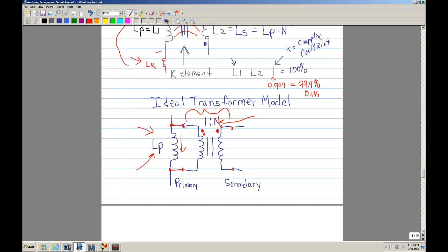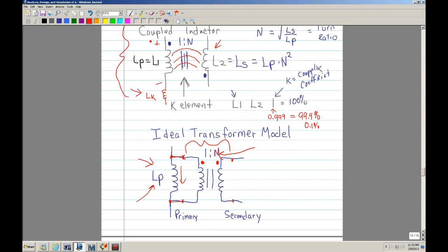Now the other thing that you need to keep track of is that typically on the ideal transformer, the phases will be in phase. Now we know for flyback they have to be out of phase. So when you make your connection, typically the diode goes up here if you use out of phase, but since the symbols are in phase, you have to put the ground here, and then here is where you put your diode, cap, and resistor.